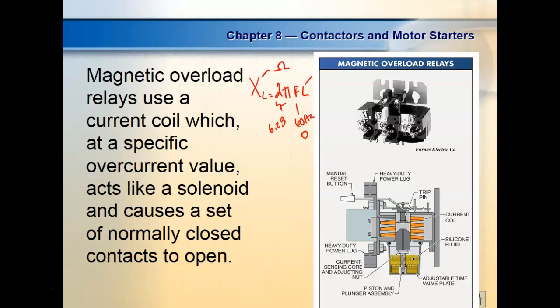Everybody understand that? Okay. Plus, AC relays are going to have laminated cores. We talked about that. What does that do? It limits the current that's induced into the core that's trying to concentrate the field. So as soon as you see that lamination, you know it's dealing with some type of AC. You can identify them real easy. Normally it'll be labeled on the actual coil, but sometimes that gets wore off, guys. Believe that or not.